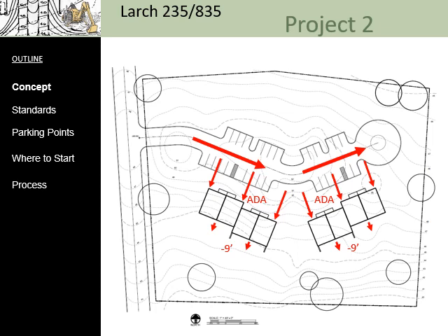You also need to make sure that at least 2 of these units are ADA accessible. You might notice in the parking lot that there is a strip of paint that is placed next to a wider parking spot for Americans with disability requirements, so you can create spaces that folks can park to get into the units. You are allowed to move these accessible parking spaces anywhere you wish into this parking lot. You do have to have them, one on this side and one on the other side, and you have to have at least 2 of these units accessible. That is a ramp, no stairs, so that they can be used in accordance with the Americans with Disability Act.